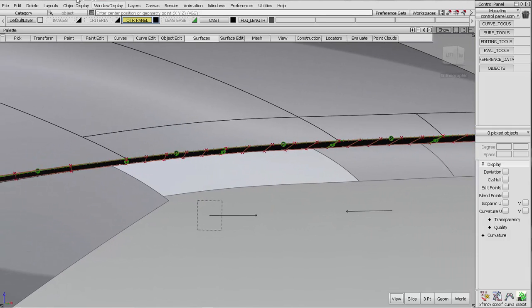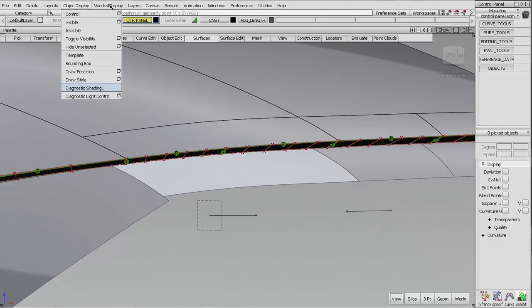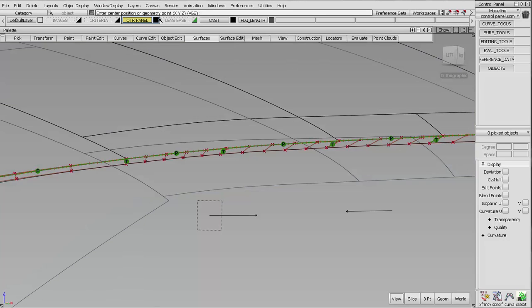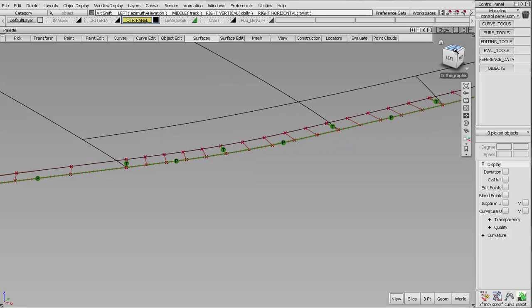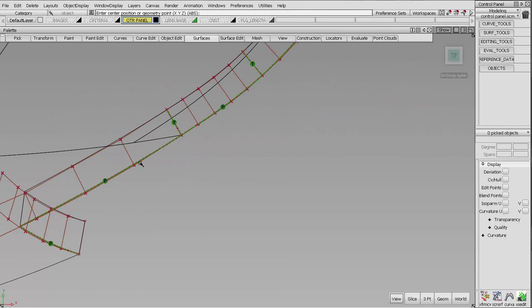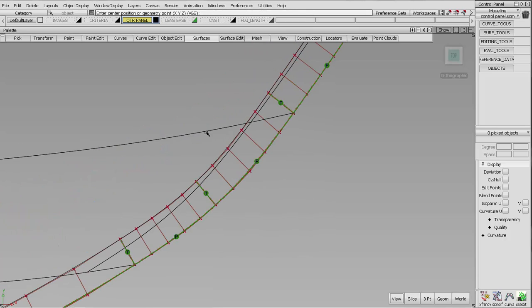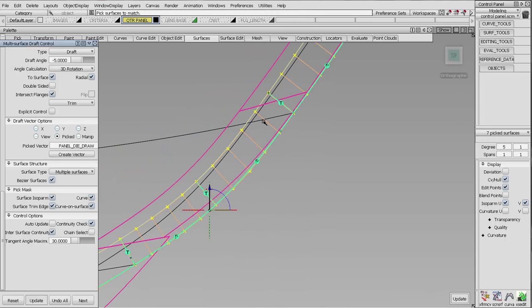An easier way to look at this might be to go into the top view. I'll turn off my construction and my length. I'll go into the top view, and you can see how radial, radial, radial, and they're fanning out. If I switch that up and we say don't be radial, they'll all point in this direction. So you can see how they're all skewed now. Same length, but now they're all skewed. Okay, so the radial option is really nice.